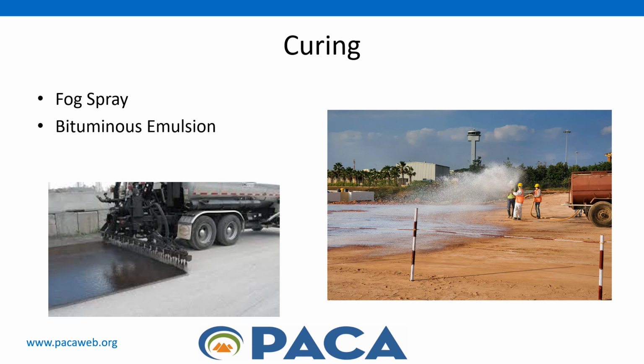Unfortunately, although not always done in practice, curing is suggested to obtain the maximum benefit from the cement treatment. If required by the engineer or design professional, the surface should be moistened with a fog-type water spray or a bituminous emulsion after the final finishing is completed.